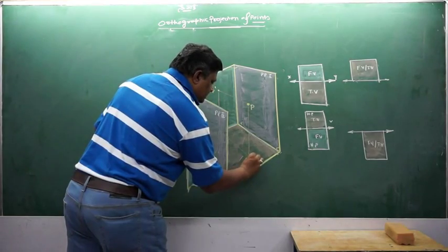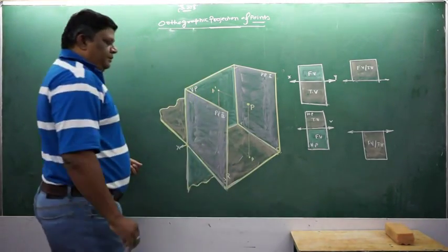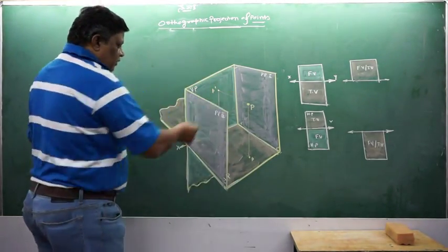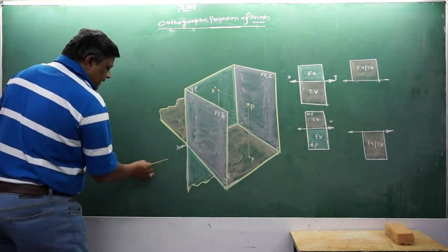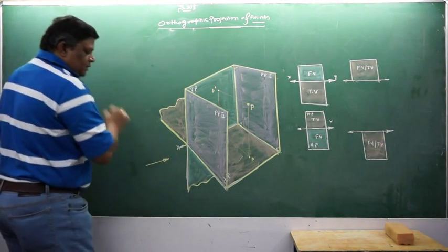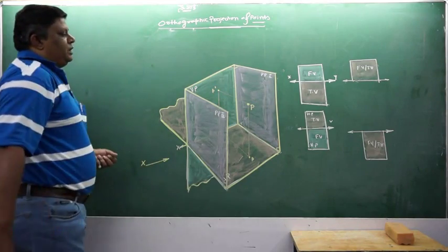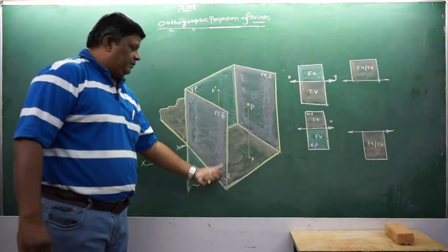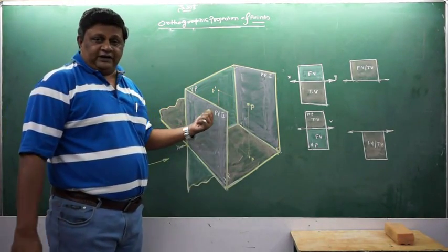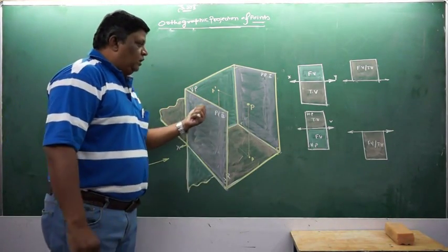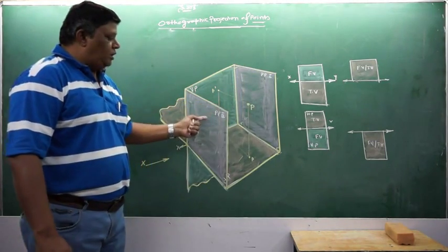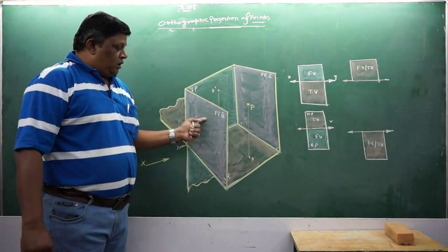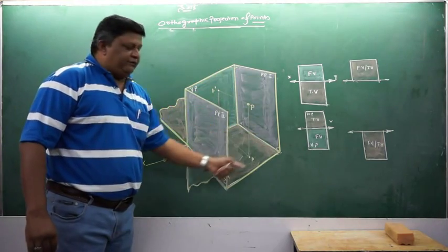The top view is coming out here as P. Say the observer is observing it from his left hand side. This is the observer. Now, on which plane will I be taking my views for the left hand side? This one or that one? PP1 or PP2? Obviously, we are dealing in the very first quadrant.